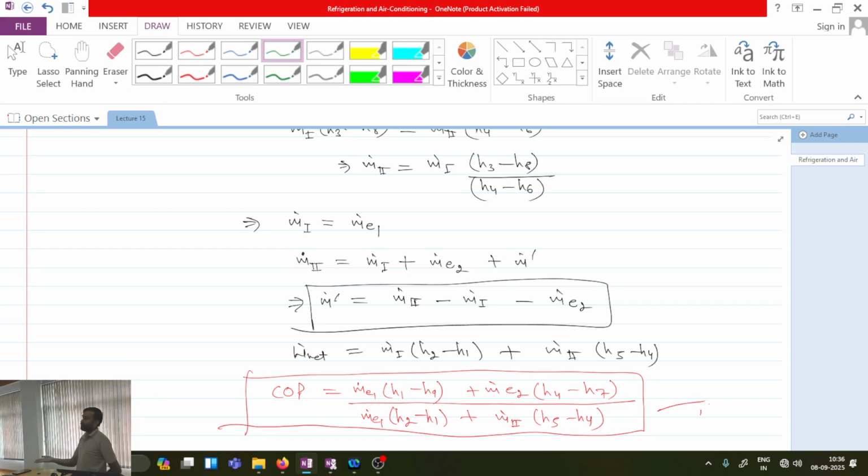At the same point of time, it will not participate in carrying the heat from liquid to vapor, and air will try to decrease the rate of heat transfer also, because the thermal conductivity of air will be very less in comparison to the corresponding liquid refrigerant. Is this point clear?